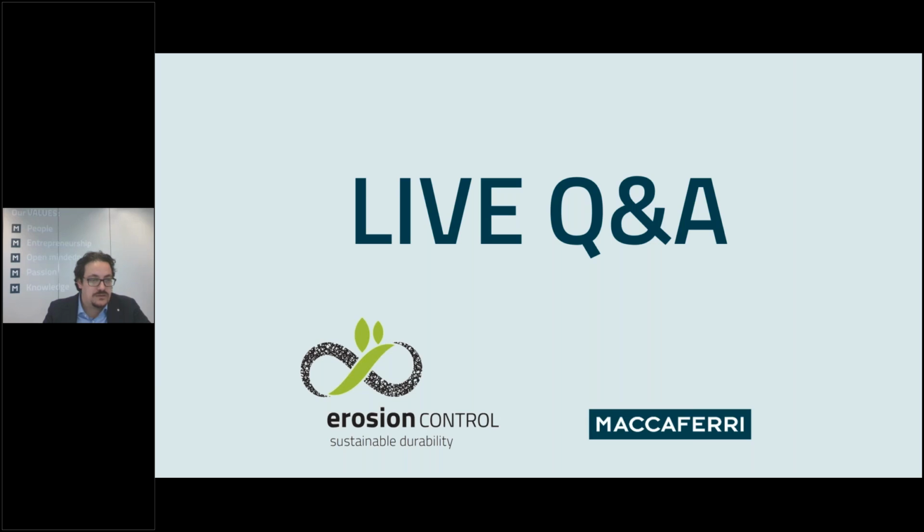Another question about what is the life of erosion control? I think that this is about the design life of the solution. So mainly you have to consider that if you use some natural fiber product for the erosion control, the design life of this solution will be only a few months, not more than 1 year, okay? And typically the degradation of this material is quite fast. So after this period, you don't have any more reinforcement function, but simply will be the vegetation that takes care